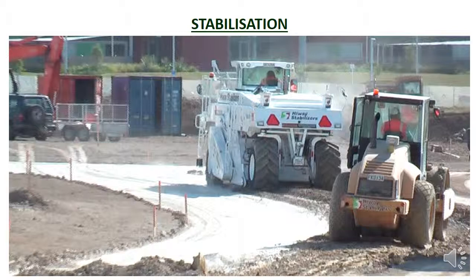The compaction and shaping needs to happen at the same time as the lime is laid, as the hardened material is very hard to shape. So you have about a day or so to shape it up.